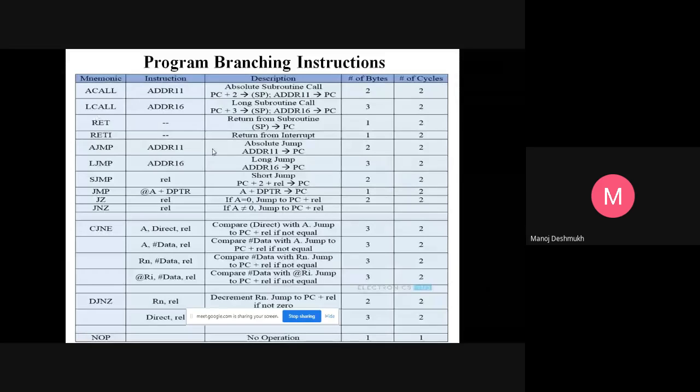So RET is for normal subroutines, and when we perform operations based on interrupts, you have to use RETI.